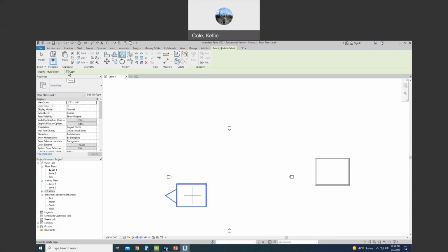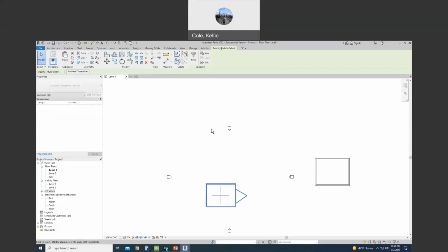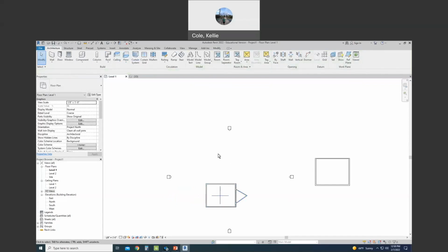notice, and there's just lots of little things to notice all the time in Revit. Right below the ribbon and before the drawing tabs, there's a little check mark that says copy. So if you don't want Revit to copy when you mirror, let's uncheck it so you see what I mean. Touch that right wall again, right? Then it won't copy, it'll just mirror. All right, let's hit escape.